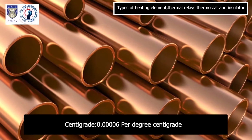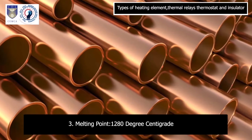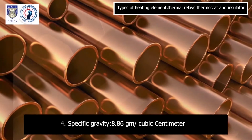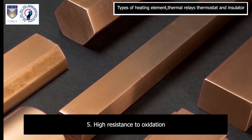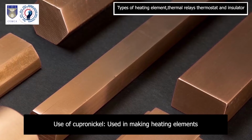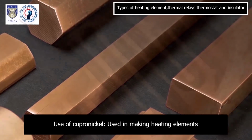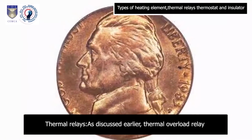0.00006 per degree centigrade. 3. Melting point 1280 degrees centigrade. 4. Specific gravity 8.86 gram per cubic centimeter. 5. High resistance to oxidation. Use of cupronickel: used in making heating elements for electric heaters and furnaces, and for making coins. Thermal relays.